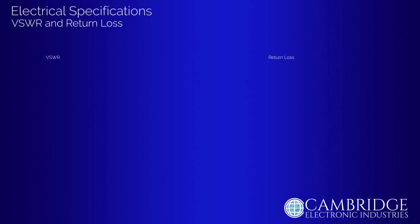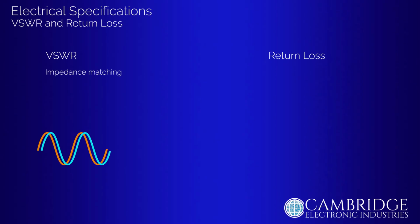Both VSWR and return loss are critical parameters for RF systems as they directly influence the signal integrity and overall system performance. Let's look at why each is important. With VSWR, the results show impedance matching. A low VSWR indicates good impedance matching, meaning that the power from the transmitter is being effectively delivered to the antenna or load without excessive reflection.